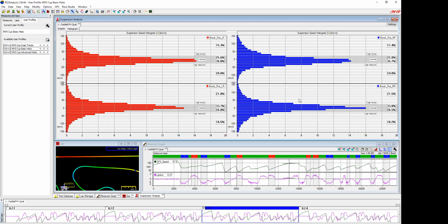So Andrew, is the velocity that the high speed, low speed transition occurs at a function of suspension travel, or is it fairly consistent throughout the jumps and rebound? It is more or less what the shock is set up internally. If the shock has adjustments, those adjustments apply at certain speeds, and your low speed will be in the shock information that you get from the company that built the shocks. They will tell you that low speed adjustment only affects stuff up to 1 inch per second of travel, or whatever the number happens to be. I think that's pretty typical though. That is what you're adjusting, what the shock manufacturer is talking about.